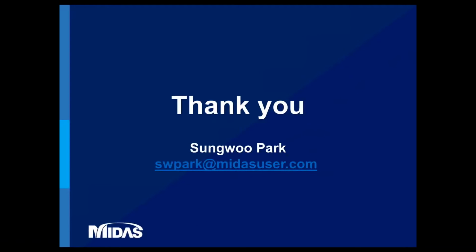Today I just covered how to model a steel tub bridge using steel composite bridge, and the node and element approach. To shorten your time, you can use a wizard to automatically create the construction stages, and before composite and after composite load.